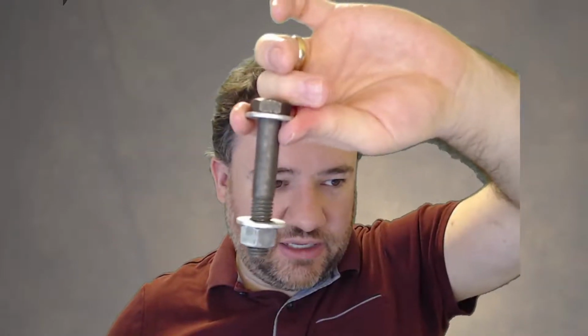Now in steel connections, you'll recall that if the thread is intercepted by the shear plane, we apply a reduction factor. There's no explicit reduction factor like that for bolted connections in wood. The reason is that we don't typically actually shear the bolts in wood connections, because the wood is not strong enough basically to shear the steel. So mostly what we have is bolt bending, and then the area of the thread will be less critical. So that's what the bolt looks like.